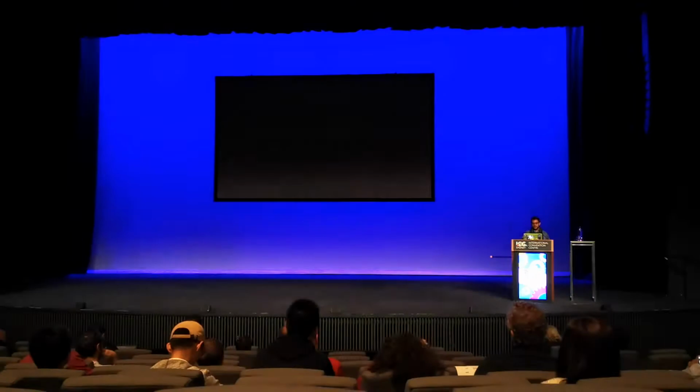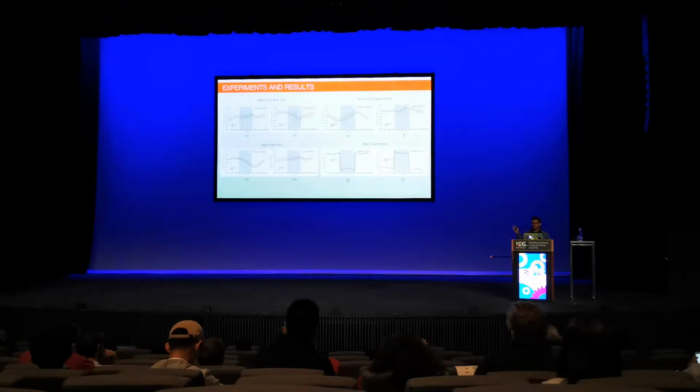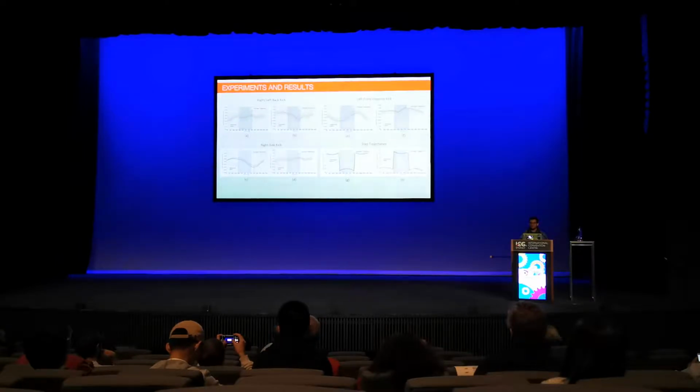So these graphs here summarize the results of the walk kick stability analysis, with the center of mass trajectories in the x and y axes shown. Each graph shows 30 center of mass trajectories for each kick direction's x and y axis, where the average trajectory is highlighted. Every combination of the graphs describes a unique kick direction where even the kicking foot can be derived.